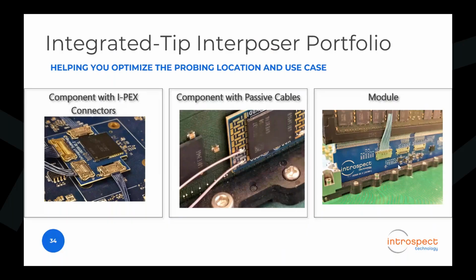So in the phase domain, it measures relative to the clock edges, and in the VREF domain, it calibrates by sweeping up and down its own VREF to find the center of the eye. And then it will give you a set of calibration values that are stored in a file, and you can adjust them if you don't like them. You can adjust the file and use those same training values.